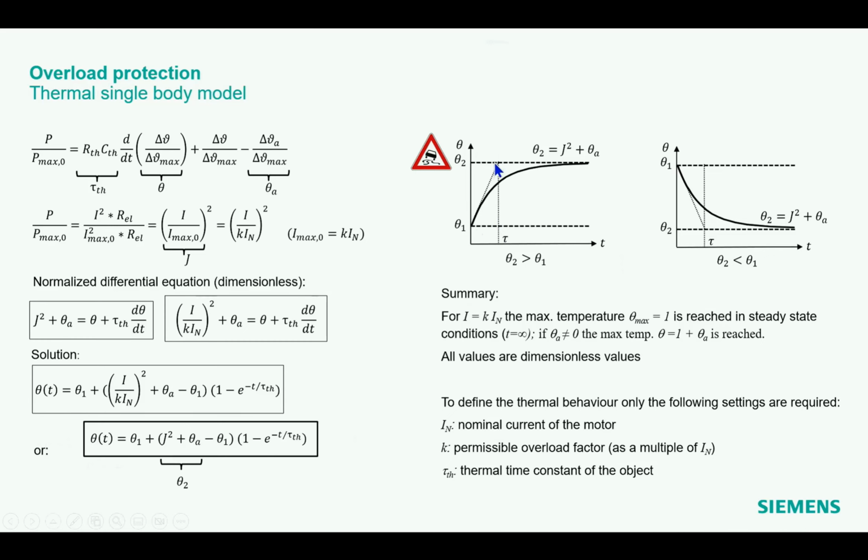You take here the inclination and you go until the end temperature. And this point is again the time constant. So if the time constant is bigger, then you stretch the curve and then it takes a longer time until you reach the end temperature at the end.